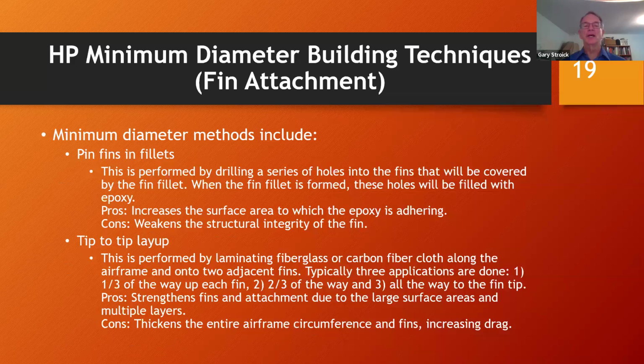So again, I mentioned the pros. The pro for this particular technique is that it does increase the surface area that the epoxy is holding onto the fin with. The con is that it's weakening the structural integrity of the fin. Those holes, when you're drilling them through, are weakening the fin a little bit. But that method has been used in a variety of ways, and it is and has been successful.